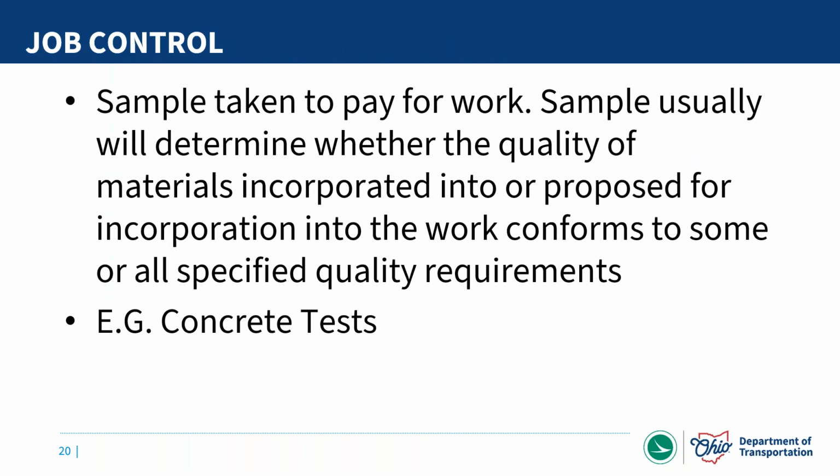Moving on to job control. This is where you will take a sample from that item to pay for work, and that sample test will determine whether the quality of materials incorporated into the work conforms to the quality requirements of that item. For an example, concrete tests. We test all of our concrete before incorporation into the work to make sure that it meets our specifications for air, slump, and yield.